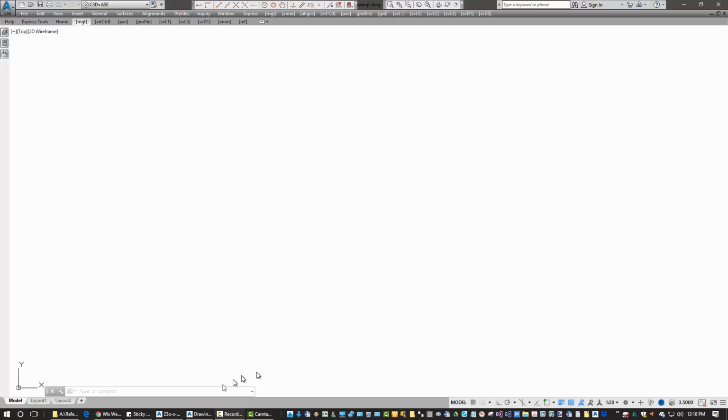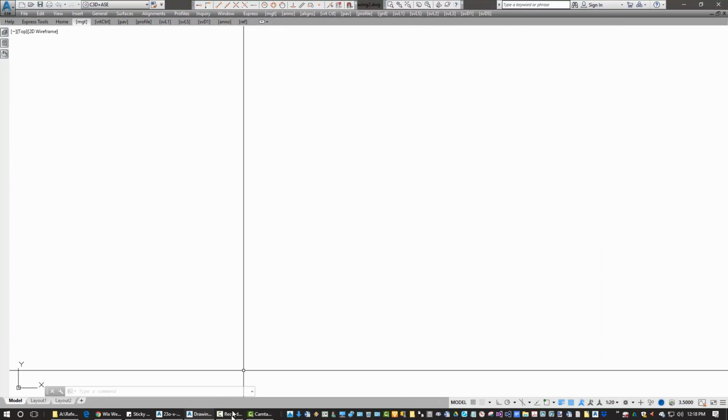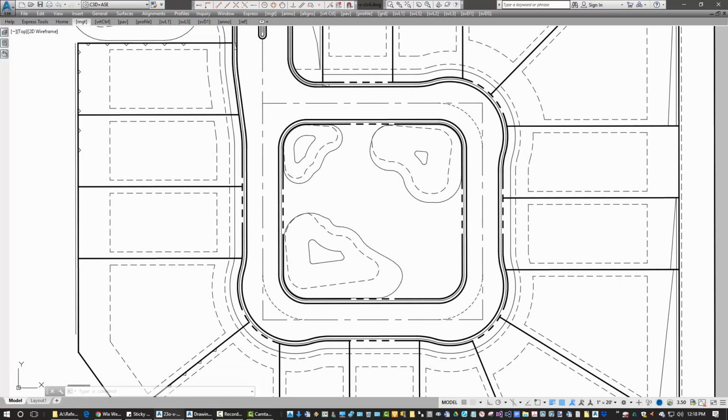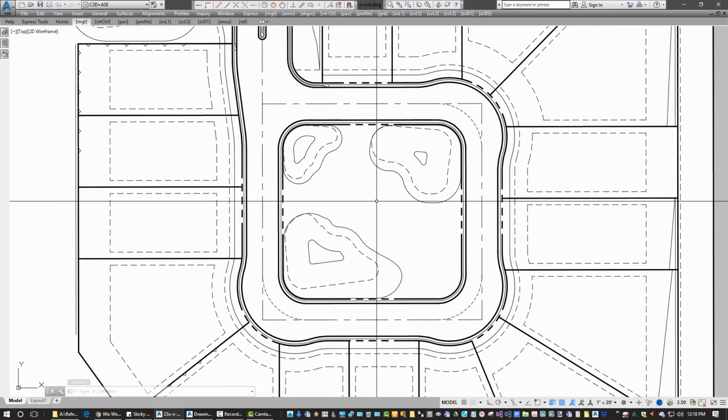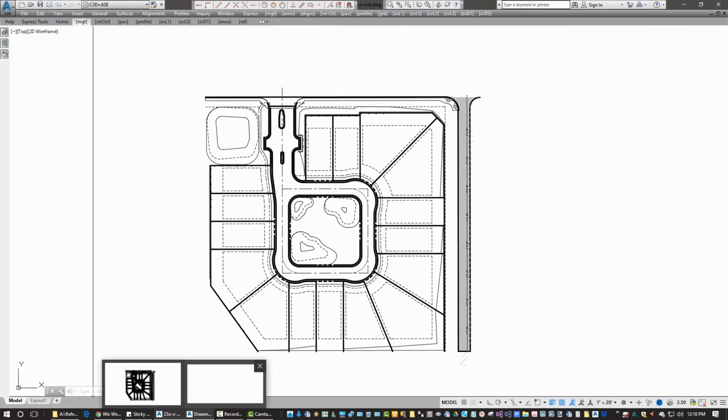So our choices here are, we could go into our site layout and use the centerline geometry here, which is perfectly fine, or we could create an alignment drawing. Whichever one you decide to go with, remember that the drawing that's used will be your alignment control drawing. For an ASE project, alignments can only be defined from one drawing. That can be changed or adjusted to another drawing, but there's a process for that.